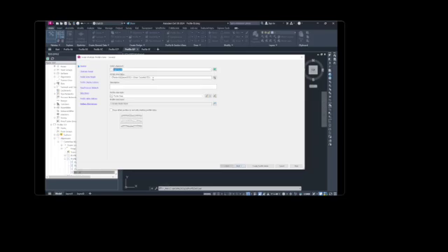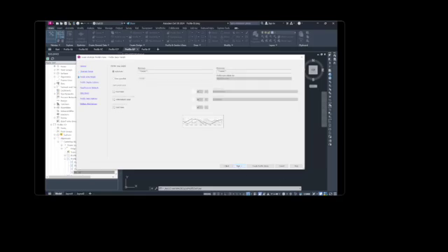Select alignment for parameters, Oak Road, profile view style, major grids. Click next. Length of each view is 500, as we said.